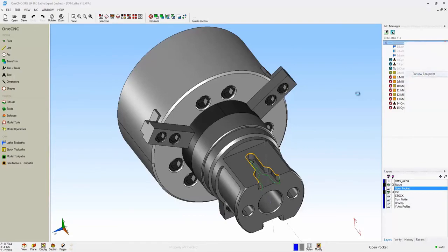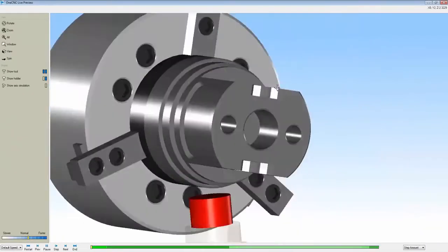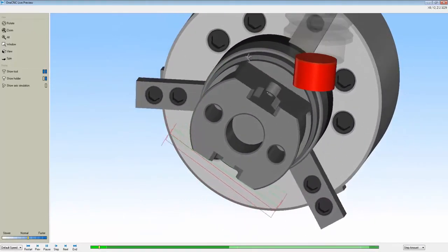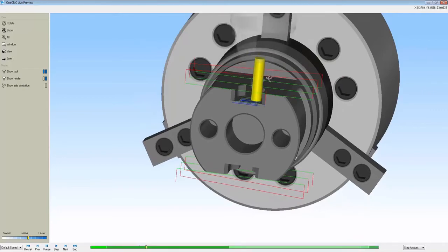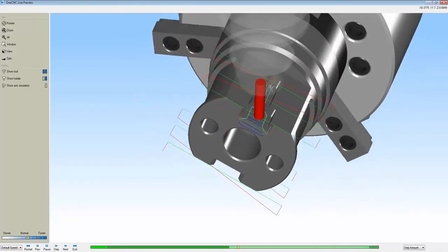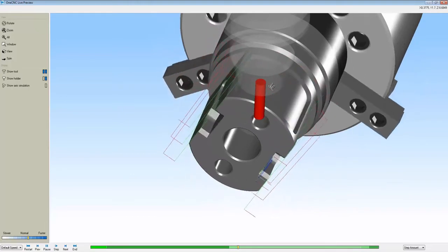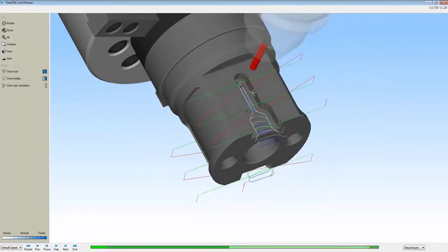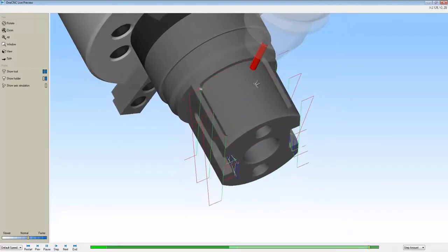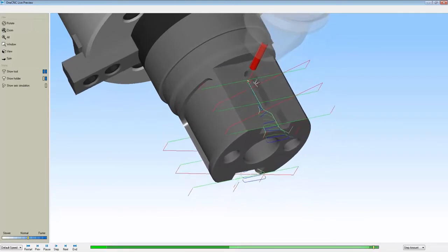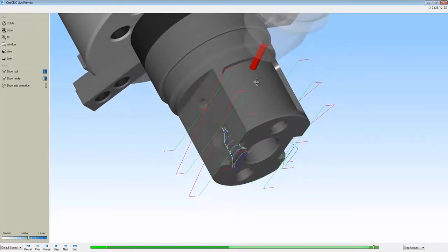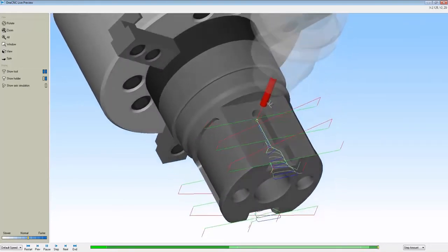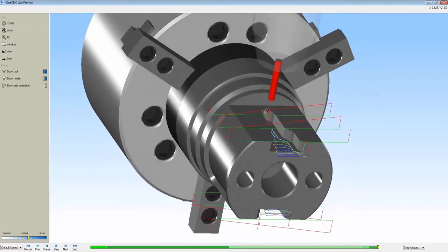We'll right-hand mouse click and select Preview Toolpaths. I'm going to rotate this around just a little bit. There we go. So we're performing some Y-axis machining. Here's some Y-axis high-speed open pocket machining along with the finish profile on there. Same thing on this side. Y-axis open pocket high-speed machining, and then a nice finish pass on there. Now we're going to come along and drill both of those holes. So there's a nice overview of the OneCNC Y-axis machining, providing the added benefit of being able to take the tool and move it off of centerline to perform your tool pass.